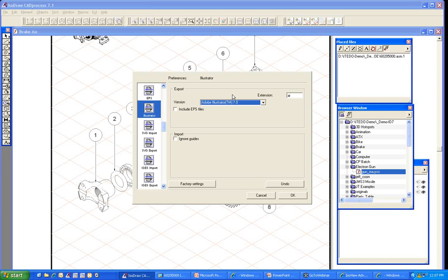So here on the Adobe Illustrator question, today Isodraw is able to directly interpret the Adobe Illustrator 7, 8, and 6 formats. It was after the Adobe Illustrator 7 format that the Illustrator format became more like a PDF file, okay? And of course, PDF has a lot of different types of variations with regards to graphics. So if you are using AI today, and you wanted to bring those into IsoDraw, you would need to save them down to an AI7.